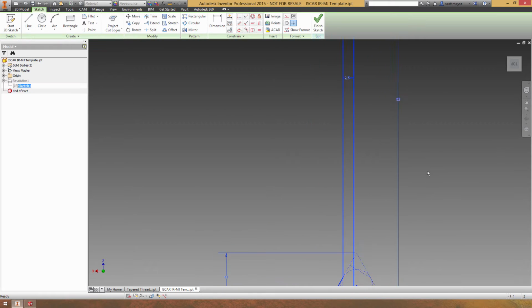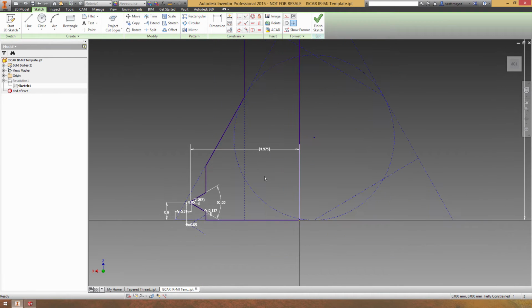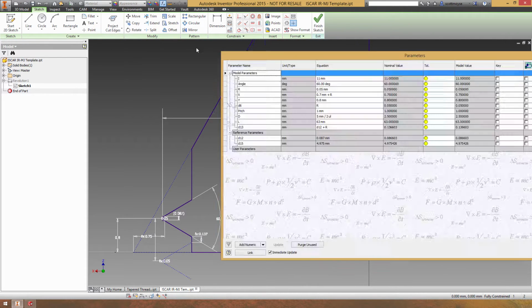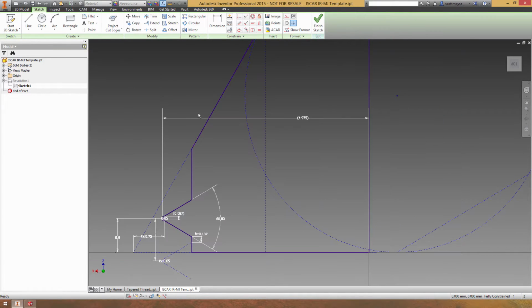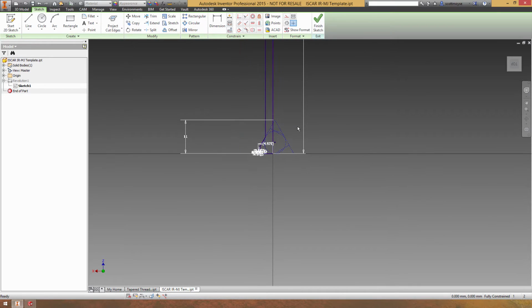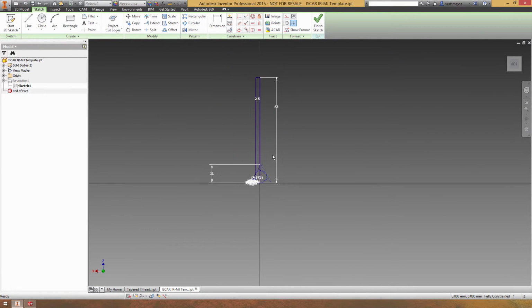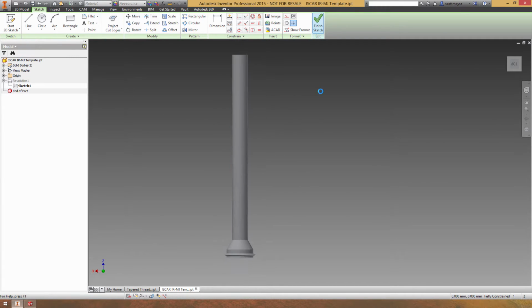Start with a sketch. Now in Inventor, I've actually created a parametric version of this tool so that in the future I can come in and adjust all these values here, which translate directly to the specifications of the ISCAR tooling. In this case, I've used the IRMJ boring bar as the foundation for the tool tip, essentially the cutting tip. So I can reuse this tool over and over again for all the different types in the future.